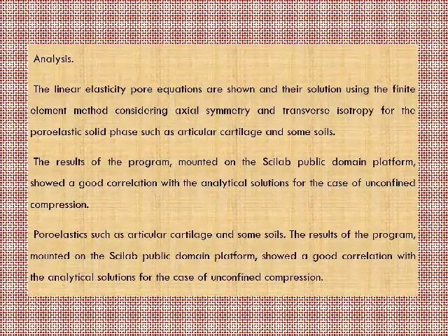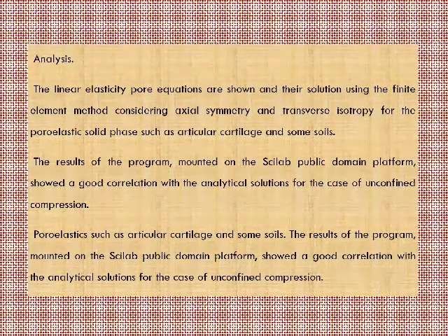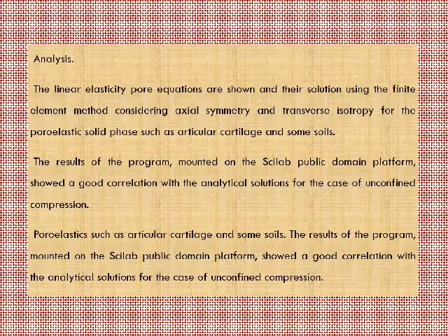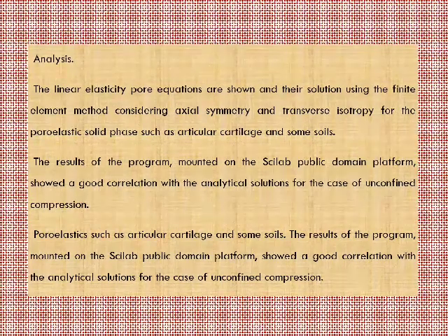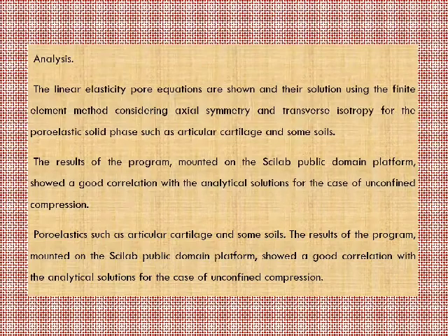And to finish that analysis, the linear elastic poroelastic equations are shown and there is a solution using finite elements method considering axial symmetry and transversal isotropy for the biphasic solid paths, such as articular cartilage and some soils. The results of the program mounted on the Scilab public domain platform,